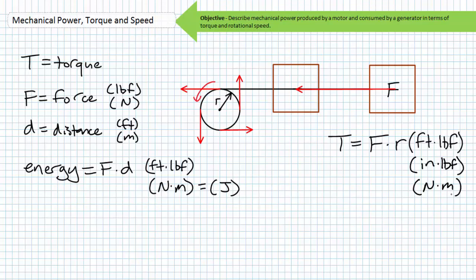Notice the similarity of units with that of energy. Torque is not energy, it's still torque, despite the commonality in units. For those with a vector physics background, you realize that energy is a scalar quantity, one that has magnitude but no direction, and torque is a vector quantity, something with both magnitude and direction. The magnitude of torque may be the same at any given point in the circular path. However, a sling stone cast at points 180 degrees opposite of each other would cast the stone in two opposite directions, which is kind of the punchline to my sling stone through the neighbor's window story.